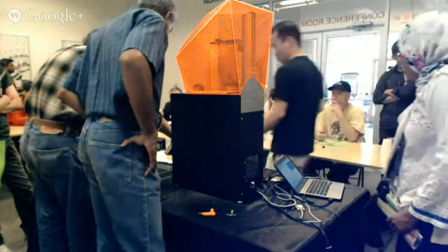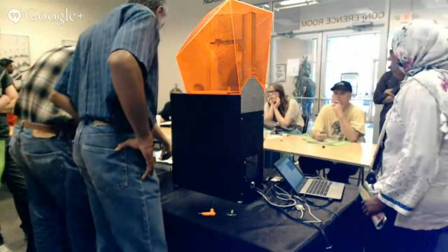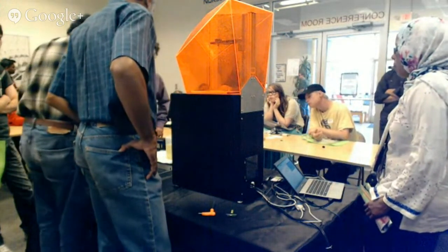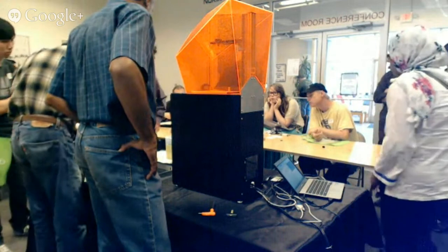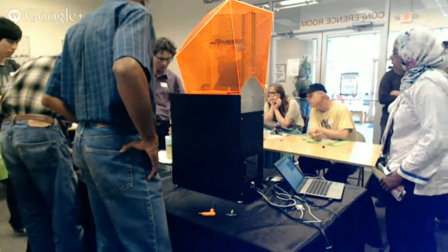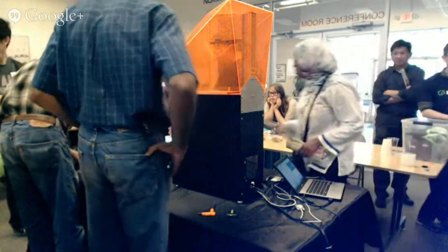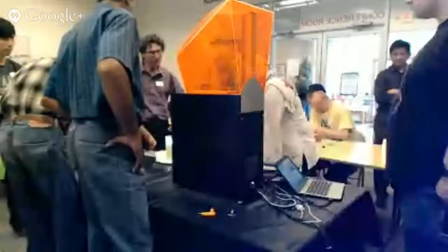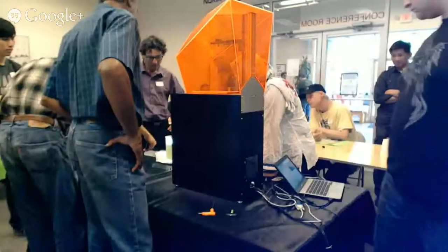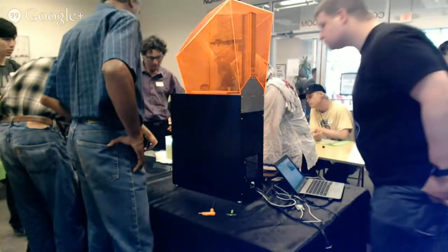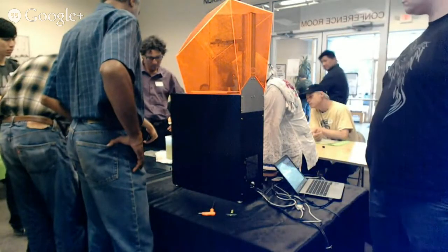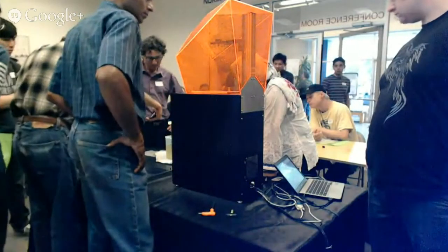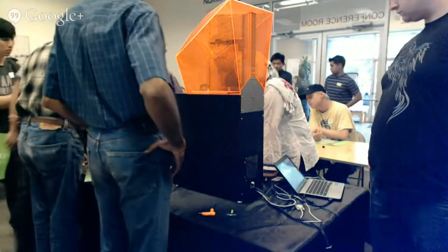So I'm still trying to understand the thickness. So you have more resin than the thickness of the layer, right? Yeah. And it looks like it's even lifted up by the build forces or something as you lift. So when you expose the light, why doesn't all that resin above the layer cure? Oh, because the resin has pigment in it, and so the light should only penetrate to a very shallow depth.